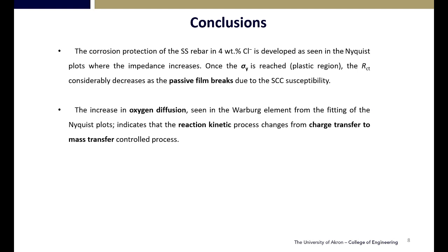As a conclusion, we saw that the passivity breakdown occurred whenever we cross from the elastic to the plastic region, as well as whenever we were close to the UTS. The increase of oxygen diffusion seen by the Warburg element was seen whenever the passivity breakdown occurred, changing our reaction kinetics from charge transfer to mass transfer.